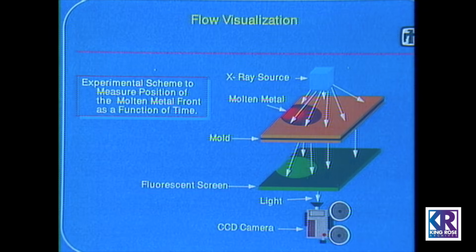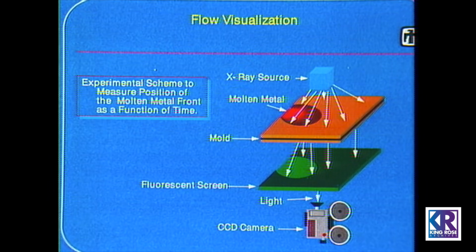The final piece of the analysis is the evaluation and optimization of a component and gating system for the casting process itself. To accomplish this, a series of experiments is being conducted with the goal of establishing rules for casting. These experiments are designed to watch the filling of a mold with X-ray images. Shown schematically here, the mold consists of a flat plate gated on one edge.